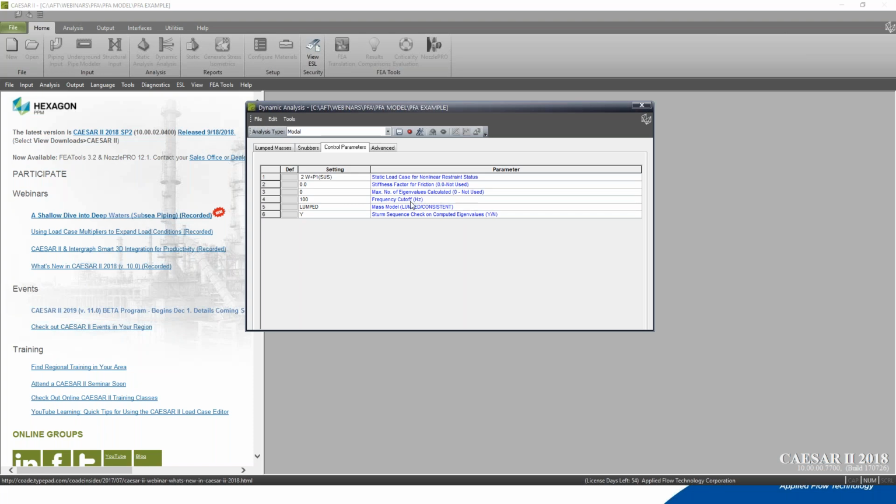In mechanical solutions, you would go for low frequencies because, as I said, they are the ones that require less energy. What you do is wipe them out of the system by putting the supports closer, because they require less energy and they're most probably the ones that will show in the field. In this case, I took 100 hertz. You can go lower if you measure lower frequency in the field.